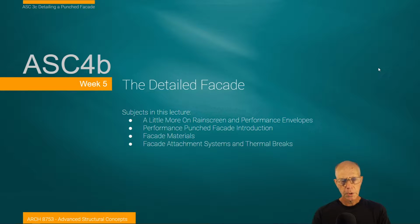So this lecture I call the detailed facade. It's really an examination of the punch facade, the idea of an opening in a wall system. It helps us to focus on the idea of reducing glazing area for increasing the performance of a wall by creating less glazed area and more highly insulated areas.